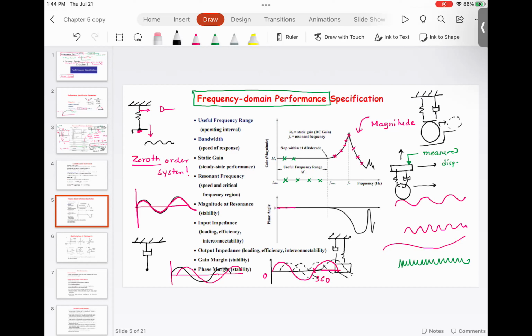So what happens when the delay is more than 360 degrees? For a minute, ignore this part. If you look at the second cycle, you would notice that as if the output is leading the input. This phenomenon happens because of the periodicity of the input, not because it's getting advanced.